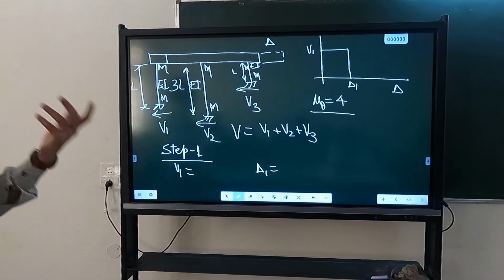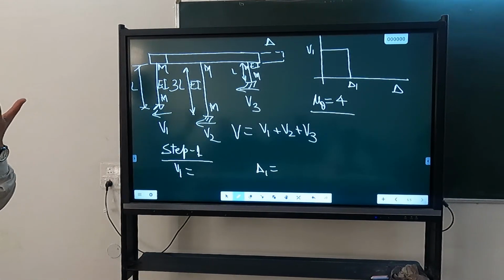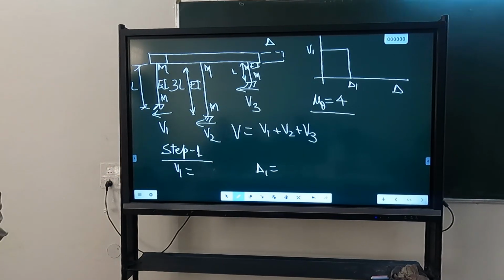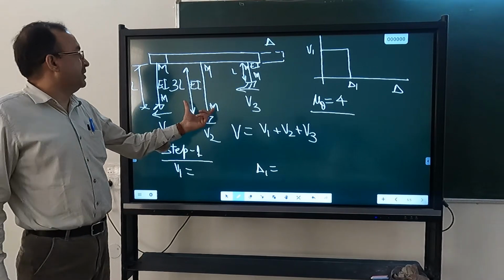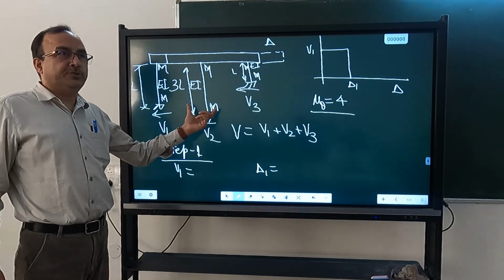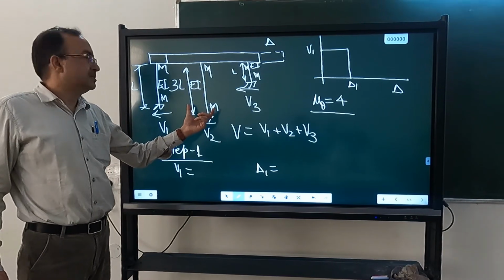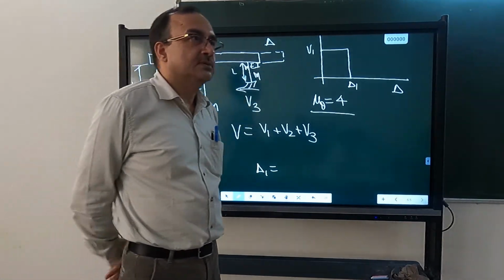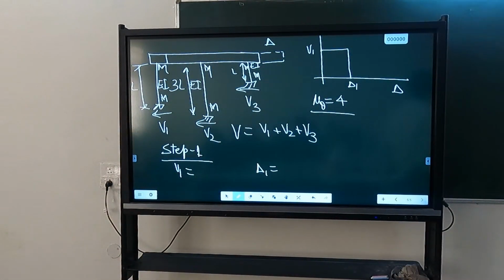Do you want your stiffness to be same? You can decide. You are making bridge. You can make anything. It's a concept. You can make stiffness same. In that case, this will have larger dia. Okay, its EI should be larger. This will have a smaller dia. I thought that you were asking in general what should be. So you are a designer.